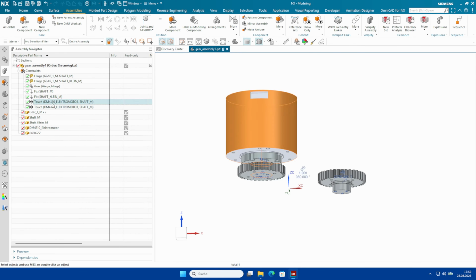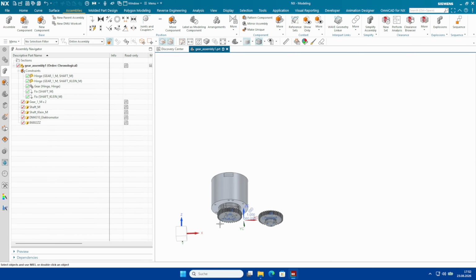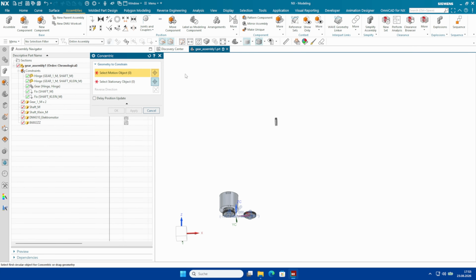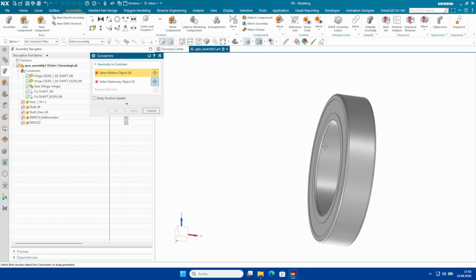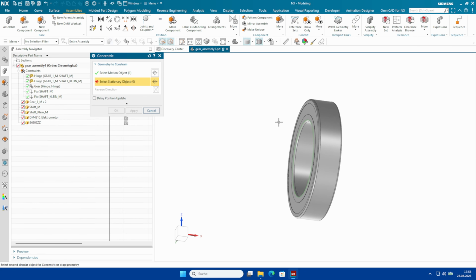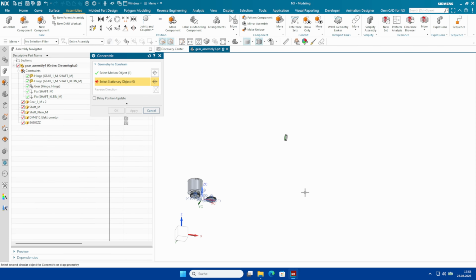Okay, and I can just delete them because I only use the constraint to align. Sometimes you can use the constraint to just align certain parts and then delete them, because that's the most efficient way to align certain part which has landed somewhere else.